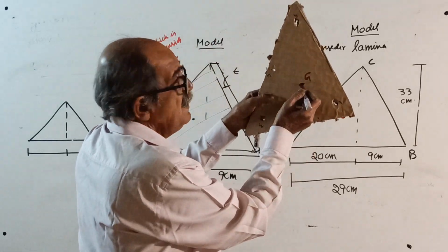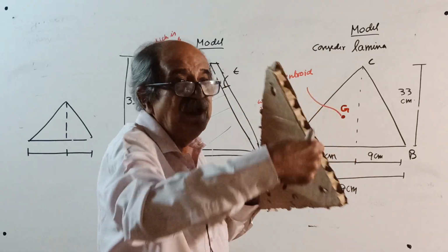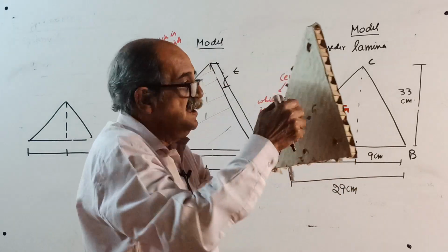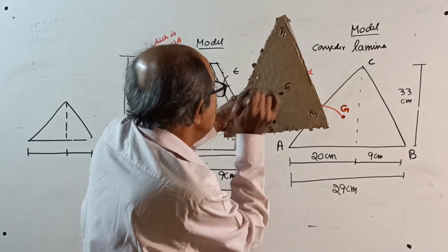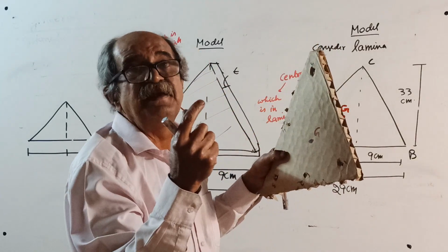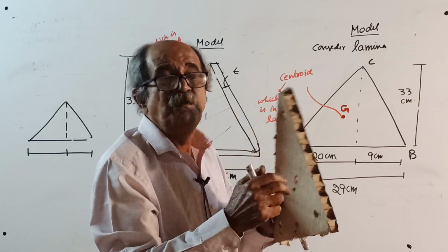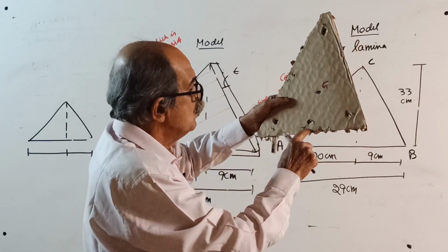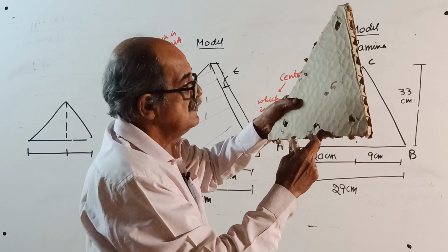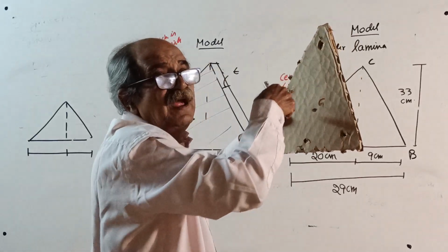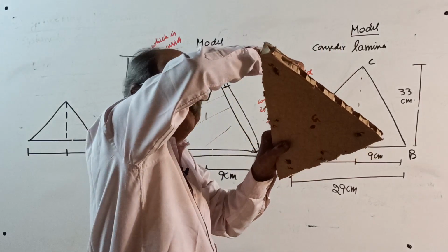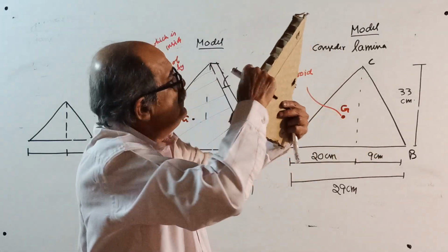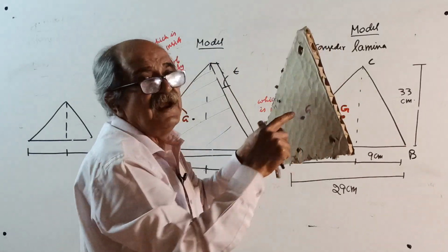And actually, the center of gravity is inside. But it is the same point; you have to go inside by half the thickness. If the thickness is uniform, you have to go inside by half the thickness. This way we don't know, you have to calculate it now. This way we don't know, but this way it is half. That is in between. You see here, the midpoint, that is the center of gravity.